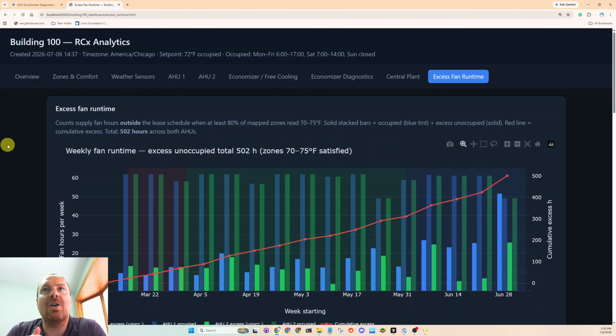But I think for this one-off stuff, assuming the data would be exactly the same every time you get it, I don't know if a data model would help me very much, as long as I can know the feeds relationships. So the most important thing is what air handling unit serves what VAV box, that kind of thing. If you can get that, the rest is just an assumption that there's one chiller plant and all air handling units have the same chilled water from that source or boiler plant.